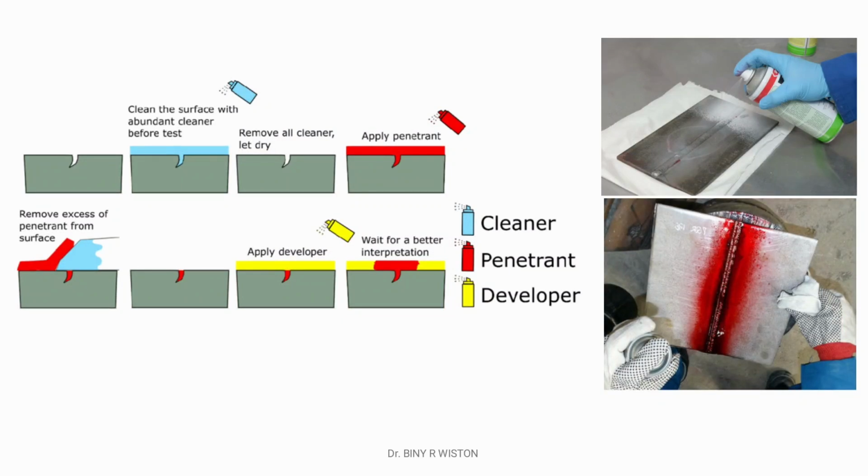The next step is inspection and evaluation. The last step in the process is the scanning of the surface for indications. The scanning may be carried out using visible light conditions or ultraviolet or laser incident light, and the defect recognition may be made with the human eye or automated optical scans. Each indication that appears should be evaluated.